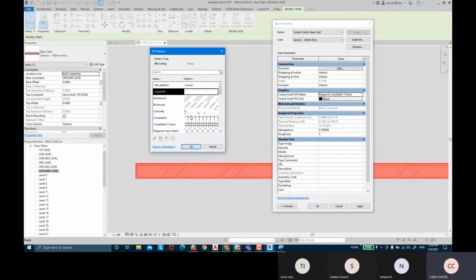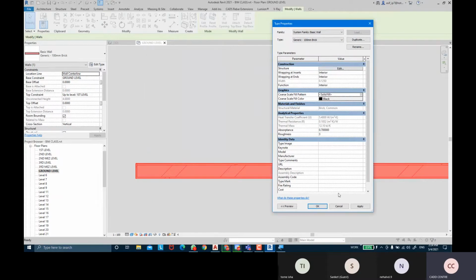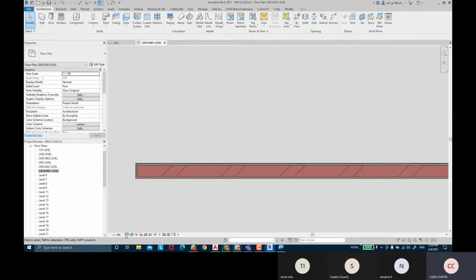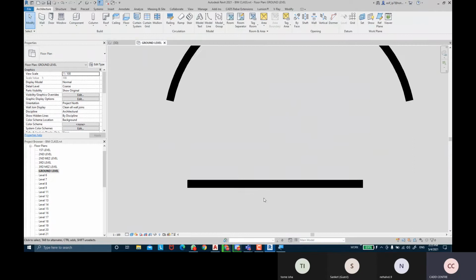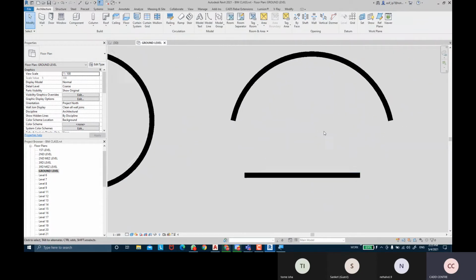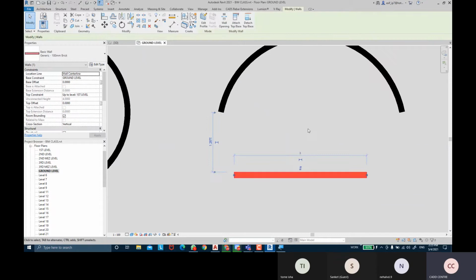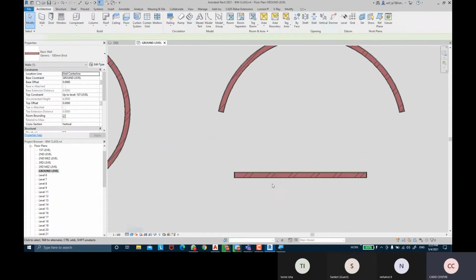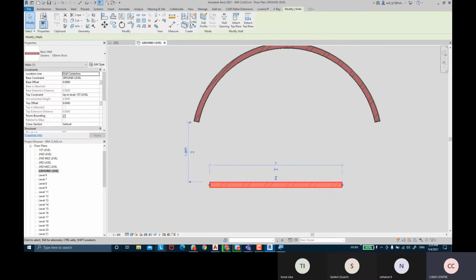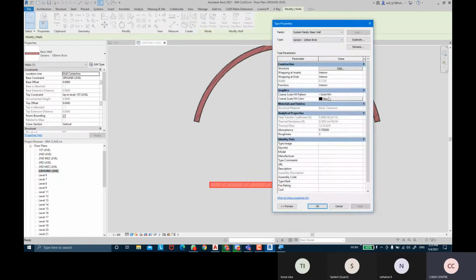And maybe if I want a solid color, I can take solid fill as well. So it will give me solid fills when I do coarse. Now if I do that, you can see all of the walls become completely blacked out. That means these are all in solid pattern. Now if I switch this to fine, it will show me fine detailings. So you can select and apply the graphical materials when you are setting the detail level to coarse.